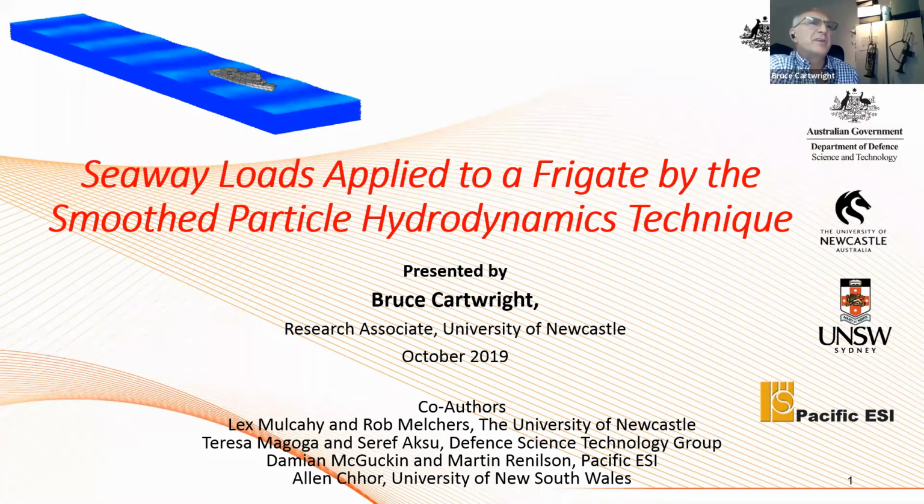Look, what we found is that typical with any of these sort of high-end engineering solutions, the most difficult part is making sure that the data is in the right format. So for our particular case, the model that we received wasn't compatible with our software. There's a lot of tools and a lot of functionality to import FE models from other pieces of software, but there was still some conversion required. So that chewed up more time than actually the time taken to build the model and define the loads on it and set up a sea state and define a tank.